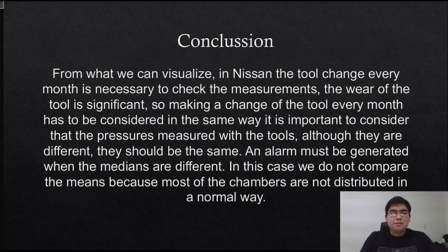From what we can visualize at Nissan, the tool change every month is necessary to check the measurements. The wear of the tool is significant, so making a change of the tool every month has to be considered. In the same way, it is important to consider that the pressure measured with the tools, although they are different, should be the same. An alarm must be generated when the medians are different.